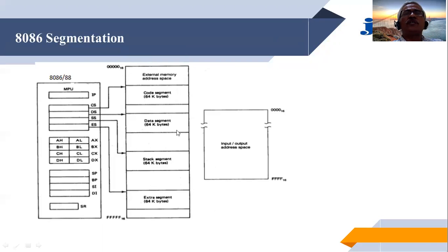Now, we know that memory is segmented, and each of the segments has its effective address, which is only a 16-bit address. But with the base value, let us suppose that this particular segment starts from address 00000. So starting from here up to 64 kilo will be one segment, and to address the 64 kilo, of course, one register is sufficient, but we have to look for the complete addressing.